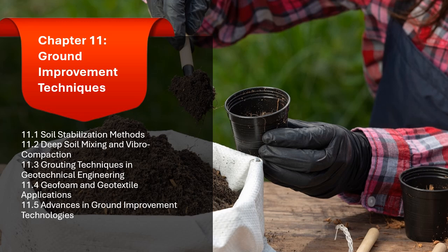Purpose: this method enhances the soil's resistance to erosion, stabilizes slopes, and can also help with the absorption of contaminants from the soil. Applications: common in areas prone to erosion, such as steep slopes, embankments, and riverbanks. 2. Microbial-induced carbonate precipitation, MICP.